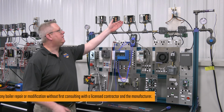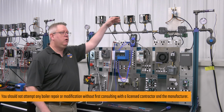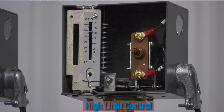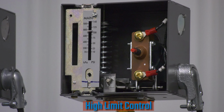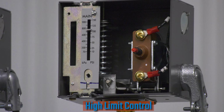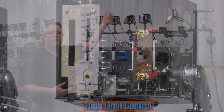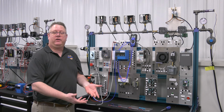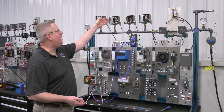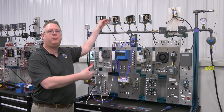We're going to take a look at the high pressure limit on our boiler. So we've looked at the firing rate, the operator, and now the high limit. And this control is what it says it is. While the operator is really our first high limit, this is our actual high limit device, which is redundant in one sense to our operating control. Its job is singly to shut the boiler off if we exceed its set point.